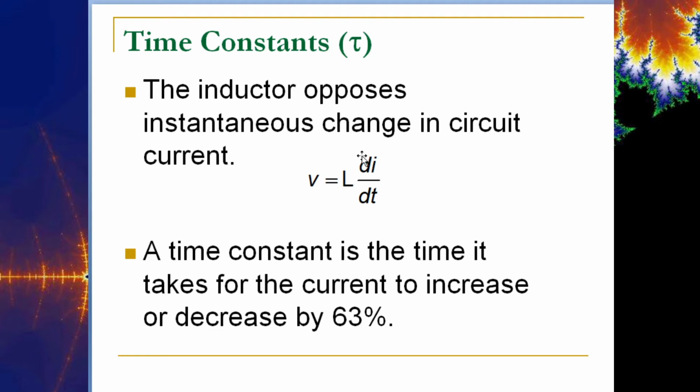However, if you do have a changing current, the inductor is going to pull some of that voltage over, and it's going to take 5 time constants to release it back to the resistance. But if it's a constantly changing current, like with an AC, it may never get back to steady state. So it could be constantly inducing a voltage on its terminals.